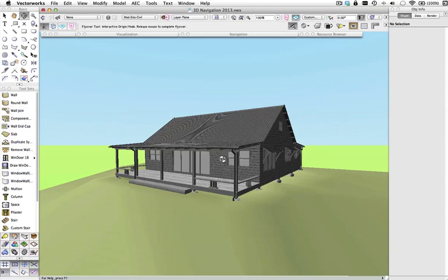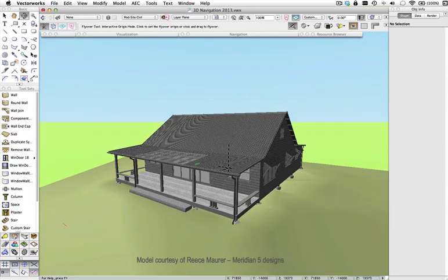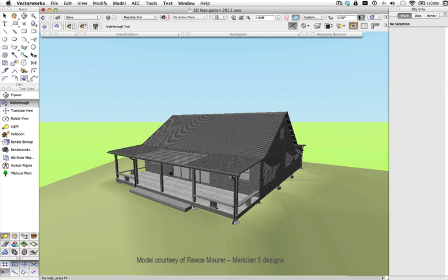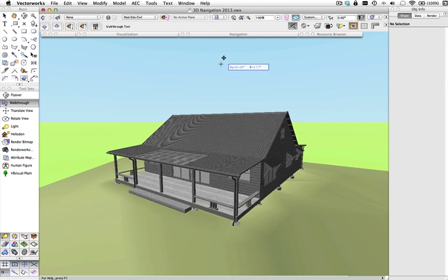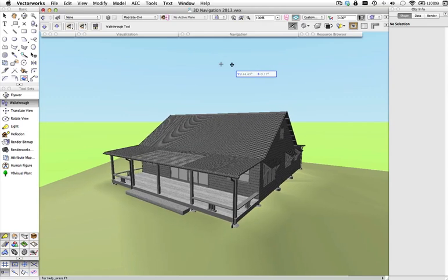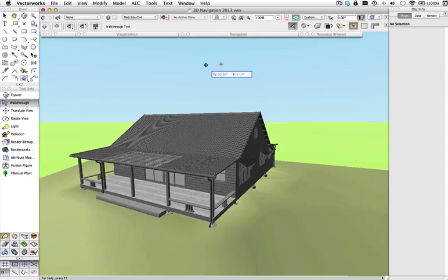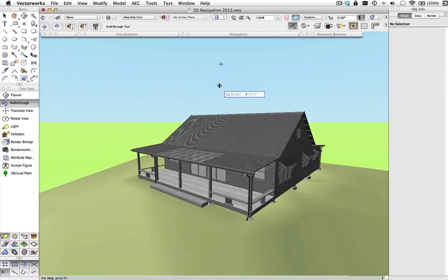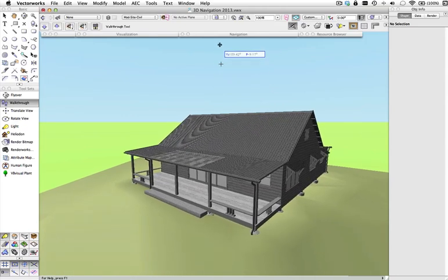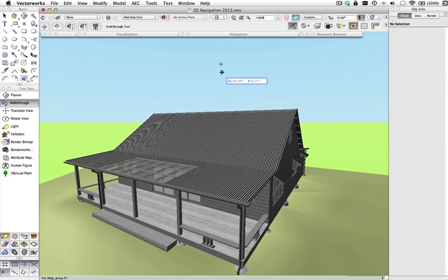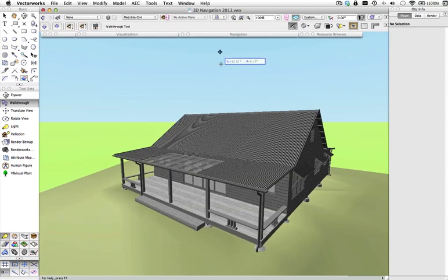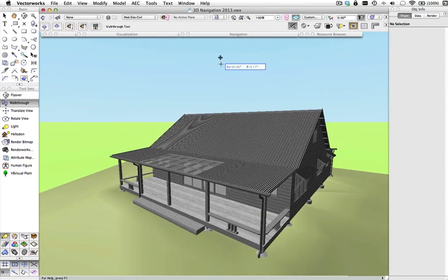Not only for flyovers but also for perspective. If we switch to perspective and go to a walkthrough, no longer will the drawing accelerate uncontrollably if you don't click in the center. You can click anywhere and you'll get a little cross or a mark indicating your initial click, and that becomes the control point. As you vary your mouse distance from that point, you'll zoom in, zoom out, go left or go right, and it's a much smoother, much more controllable environment for actually manipulating a perspective.